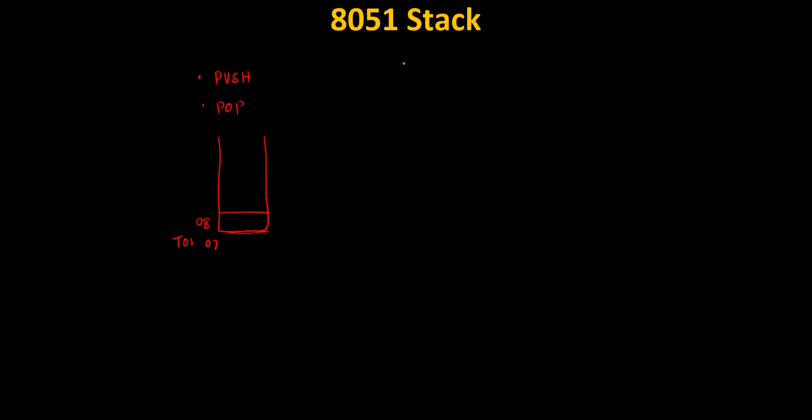So the top of the stack always points to the location before the next free one. When you are going to push data, this is pointed to by the register SP, the stack pointer. The stack starts at address 08.